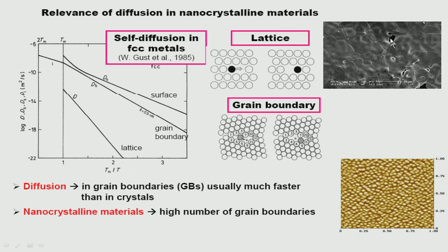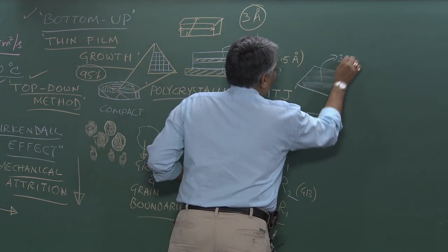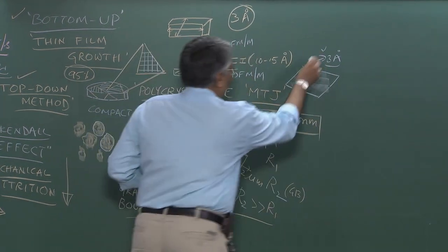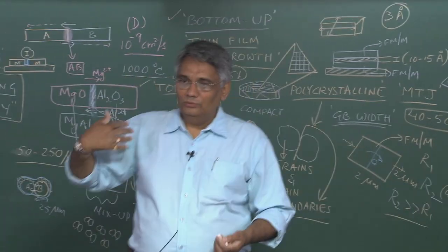And the problem in a polycrystalline material is you also have the formation of these voids. There is nothing there, right? The voids are deadly for any device application. And when you transform this into, again, between these two steps, there is also an intermediate step where you get a completely smooth thin film. Okay, that picture is missing here, but you can transform this into a completely smooth crystalline thin film with a surface roughness of the order of 3 angstroms. That's not a problem.